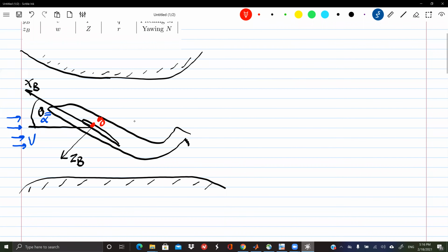Let's write down the equation of motion in an MAE 80 setting. Just basic, simple, forget what you learned in this class. I'm giving you a body that has 1 rotational degree of freedom, theta. What is the equation of motion? Well, the equation of motion from MAE 80 is I theta double dot equals the torque, correct?